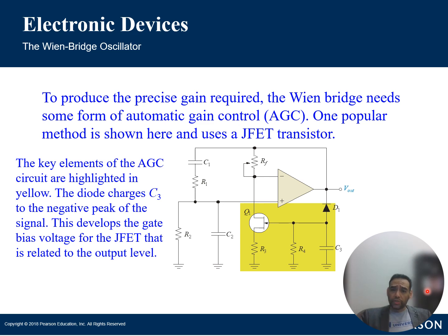The phase condition, this occurs when the impedance of that resistor capacitive series network equals the impedance of the resistor in the other arm of the bridge. So you can use this for design to determine what your values are going to be. And what this does, it balances it, provides balance there. I'll say that. I don't think I said it right, but it's close enough.